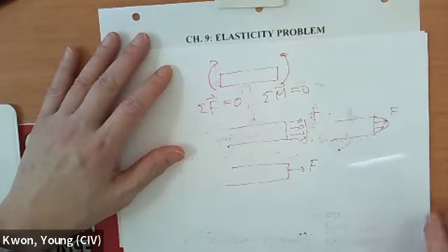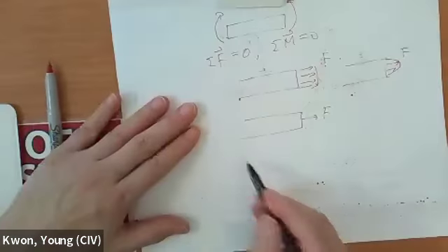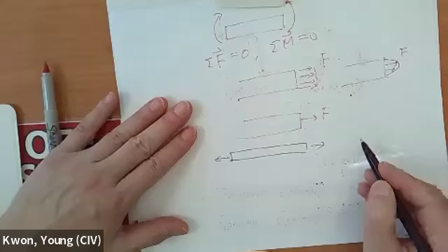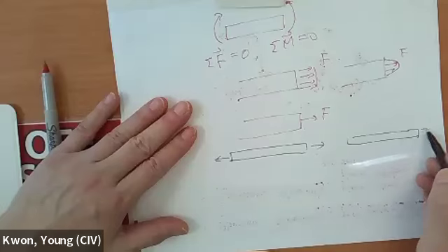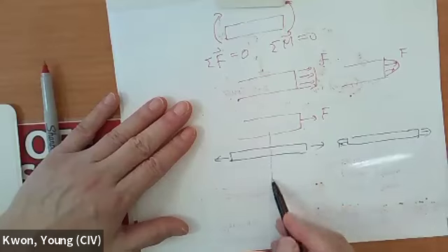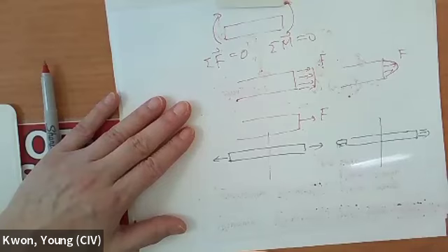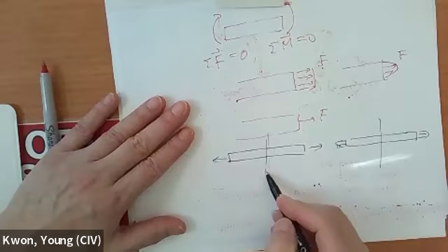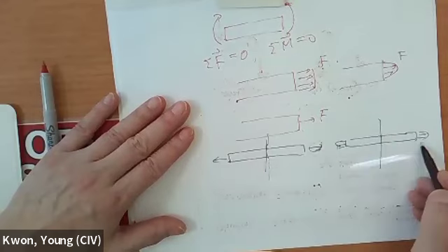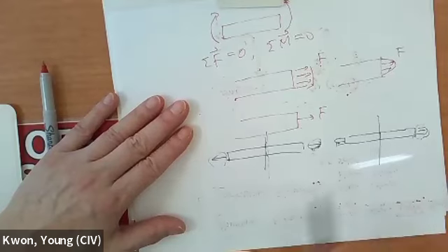Then, when is this critical? If you have a member subject to force like this, or subject to force like that, then, for example, in the middle, using the so-called Saint-Venant principle, the stress here and the stress here are going to be the same regardless. The actual load applied is going to be different, as long as the total is the same.